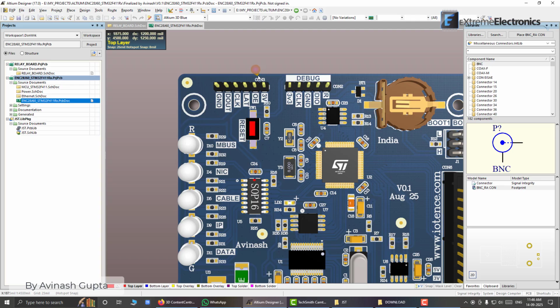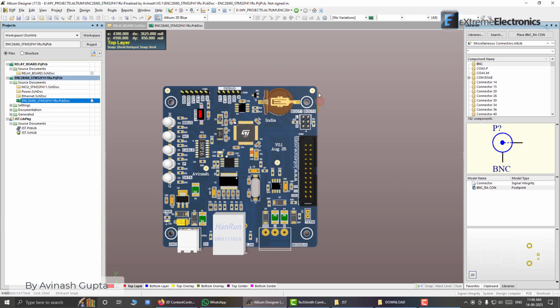So our aim is to make our relay board compatible with this connector, so that we can plug a header or wire here, and from there connect our relay board and place it next to this PCB and control our input output relay board through this shift register without wasting the precious GPIO pins of the microcontroller.